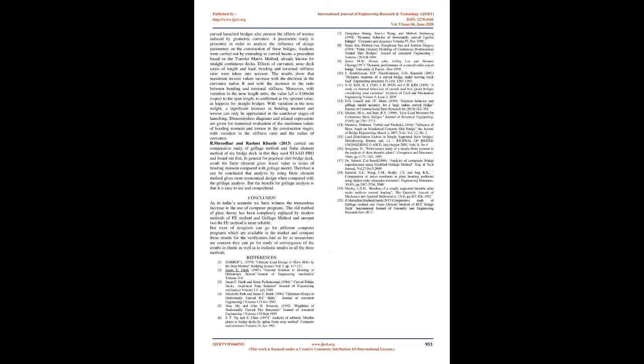With variation in the nose weight, a significant increase in bending moment and torsion can only be appreciated in the cantilever stages of launching. Dimensionless diagrams and related expressions are given for numerical evaluation of the maximum values of bending moment and torsion in the construction stages, with variation in the stiffness ratio and the radius of curvature.